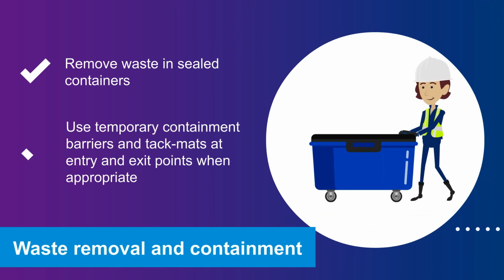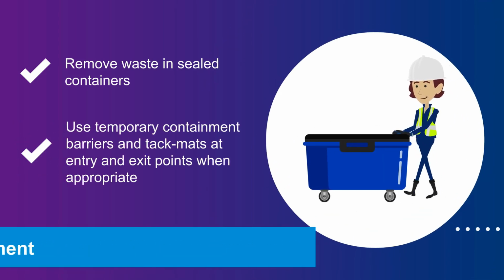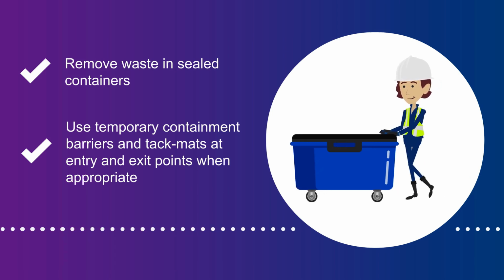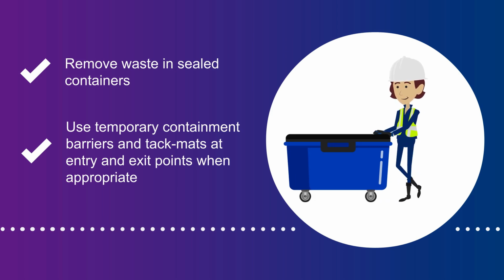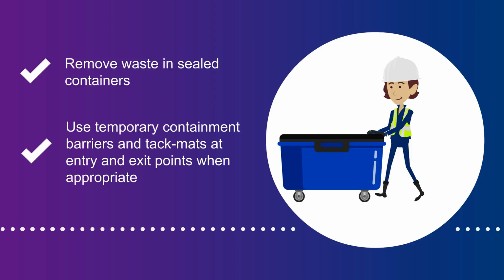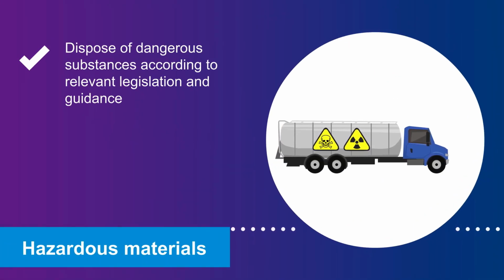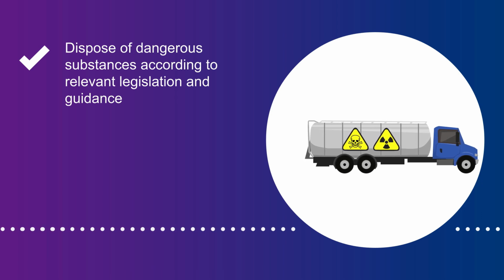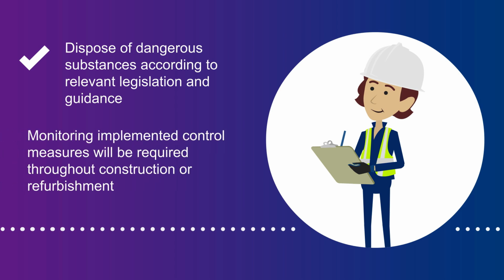Waste removal and containment. Remove waste in sealed containers. Use temporary containment barriers and tack mats at entry and exit points when appropriate. Hazardous materials. Dispose of dangerous substances according to relevant legislation and guidance. Monitoring implemented control measures will be required throughout construction or refurbishment.